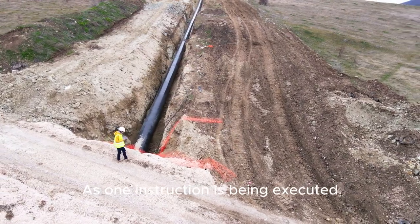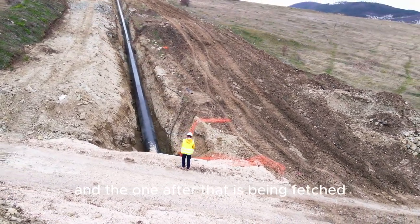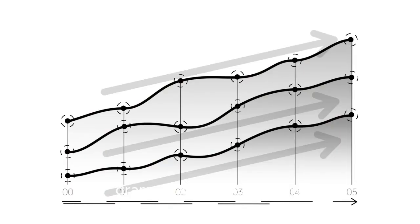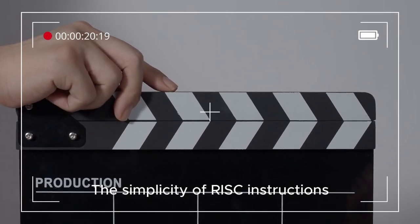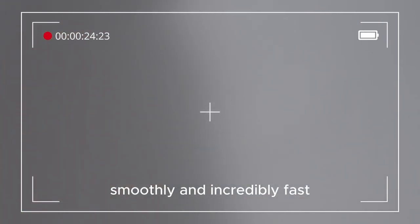As one instruction is being executed, the next one is being decoded, and the one after that is being fetched. This creates a continuous flow of instructions, dramatically increasing the processor's throughput. The simplicity of RISC instructions makes this assembly line run smoothly and incredibly fast.